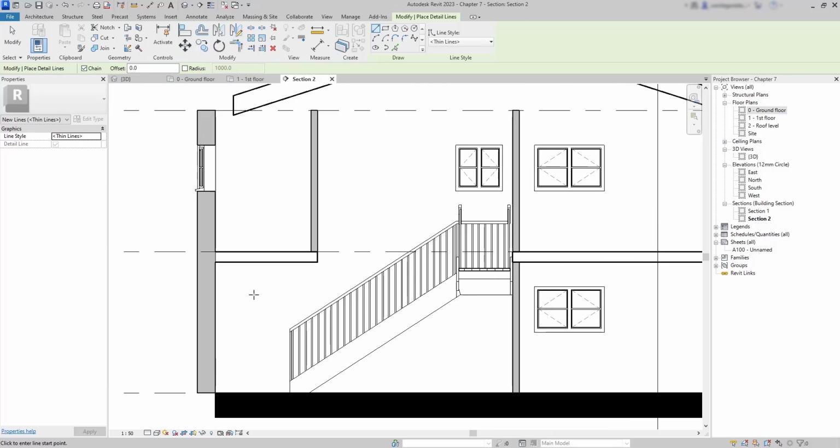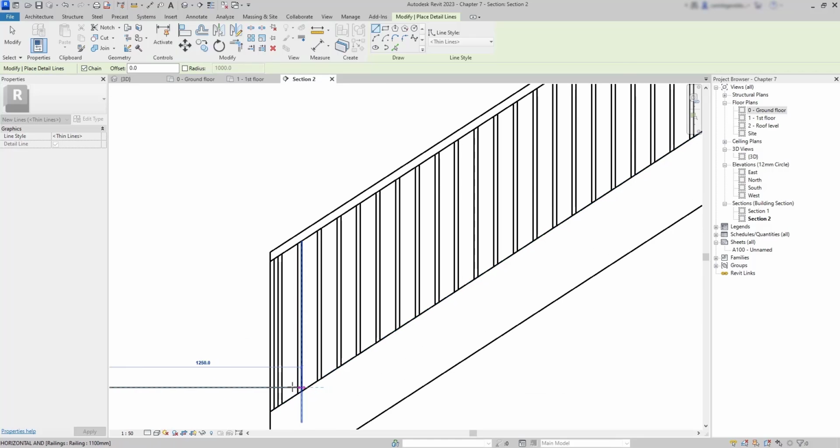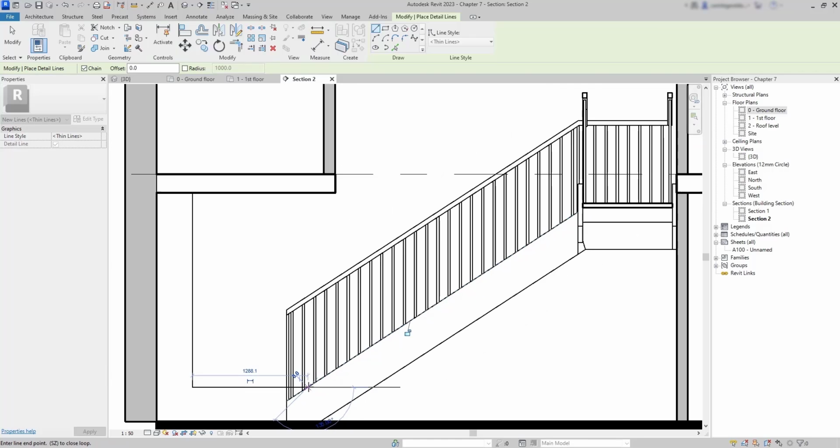Let's start drawing the line from the floor. I'm going to make the height 2200 mm of length. Then draw a new line to the right until it matches the exterior support of this stair. Finally, I make another line, this one vertical, to intersect with the floor, and press escape at the end.